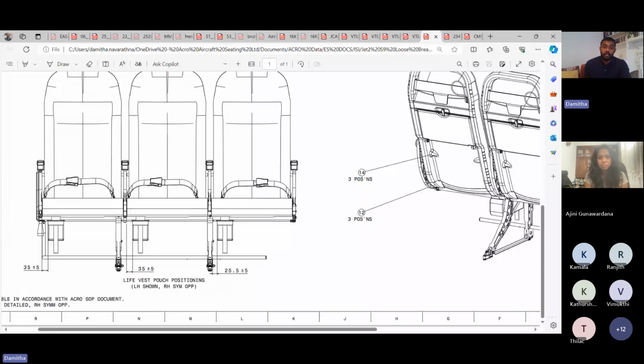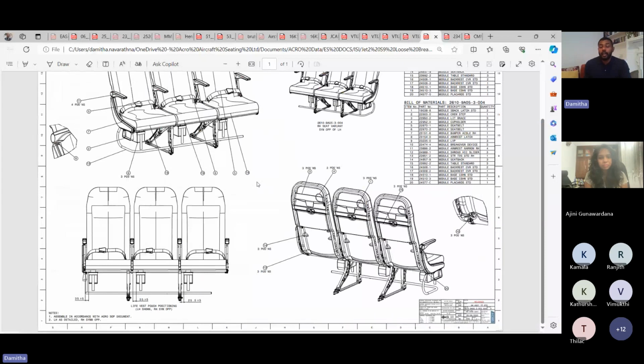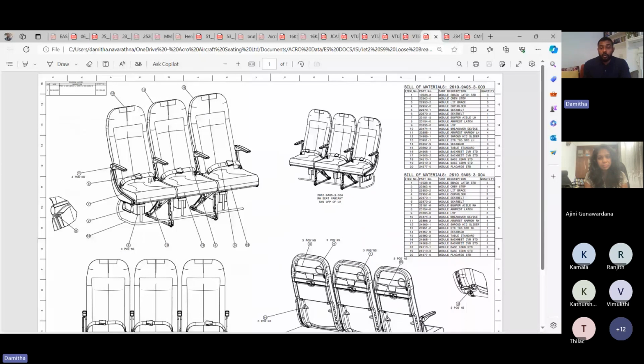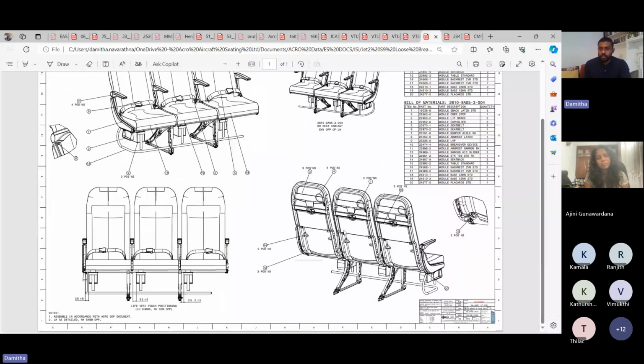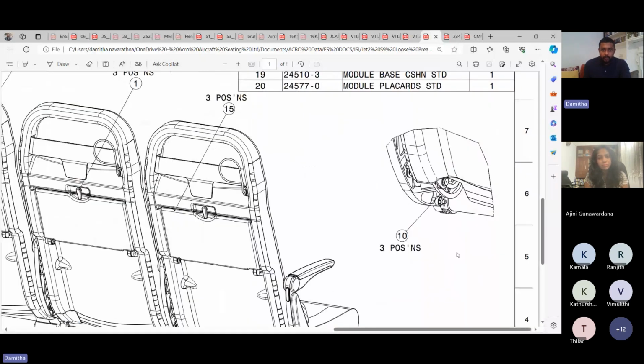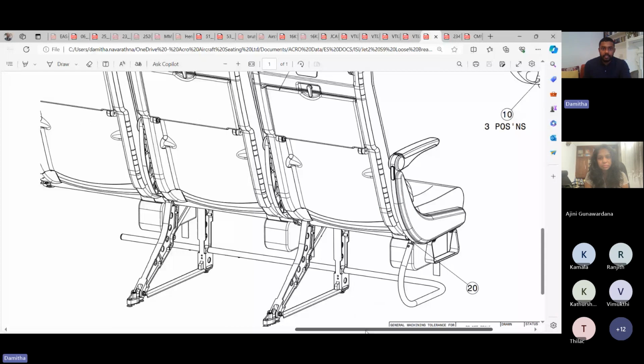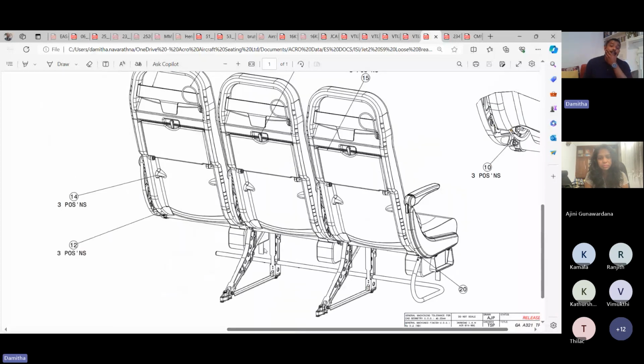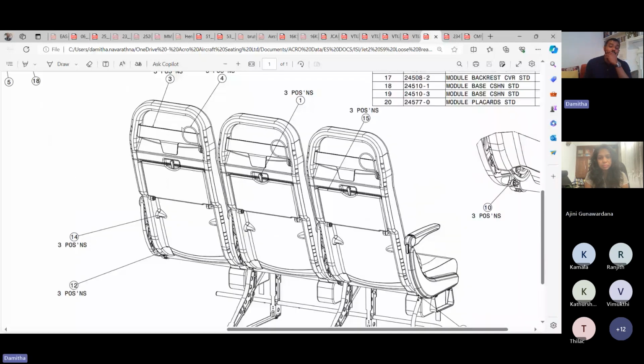This is again regulated. When you're testing the seat, you put a big dummy in here and do the testing and make sure the seat belt doesn't come off and it doesn't have pressure points in the belt that harm the passenger. And as I told you, the seats are made in a way that in case of an accident, the seat back meets the head injury criteria requirement.